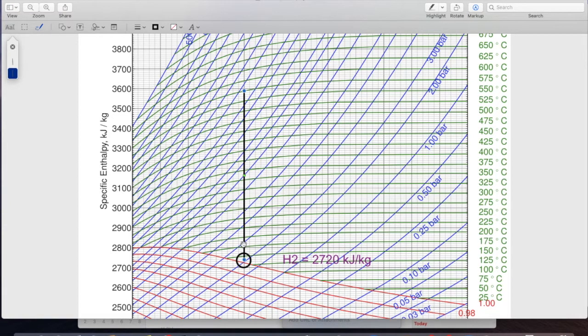First thing we need to figure out is how high a pressure do we think we can get away with? Well, the one thing that I know is for a 150 class flange, which would be for a low pressure steam system, the limit is 275 Celsius and about 1100 kPa.